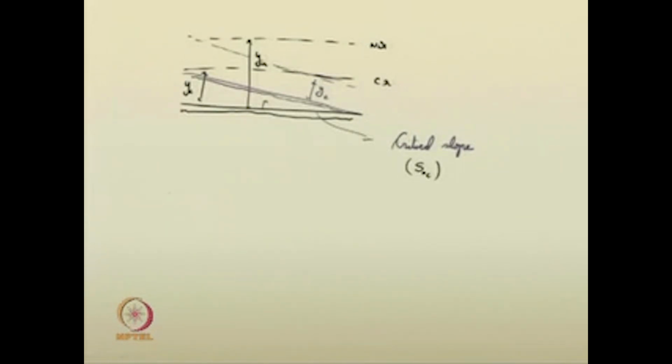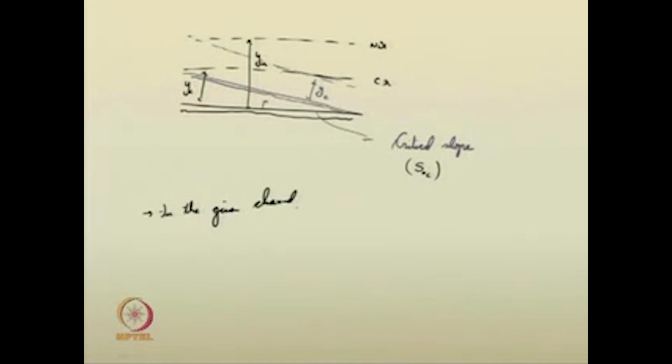Now, for the given channel, or whatever possible limit at which you can raise the bed of the channel. If you raise the bed of the channel beyond this, then supercritical flow occurs. If it is lowered further, subcritical flow itself will be prevailing, like that you are aware now. The limit for this particular channel at which the critical slope exists, that is called limit slope.